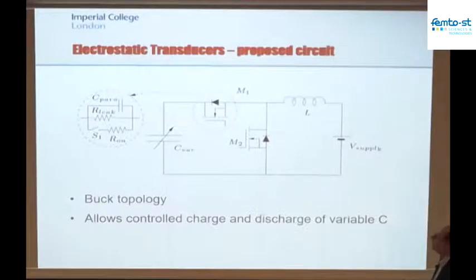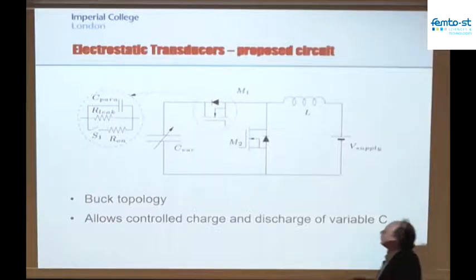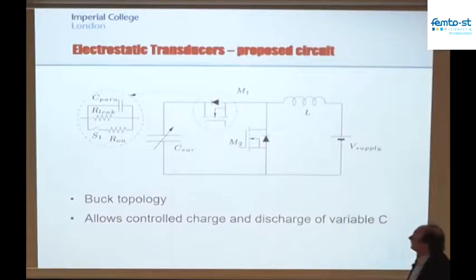So we looked at some circuit optimizations where we were literally optimizing the width, length, and doping ratios of the MOSFETs to get the best overall performance out of this type of electrostatic harvester, knowing that the variable capacitance was extremely small and the total amount of charge we had available was extremely small. And that basically means that if you're designing this sort of energy harvesting system, now we've got to know something about mechanics because we've got to understand the mechanical system.